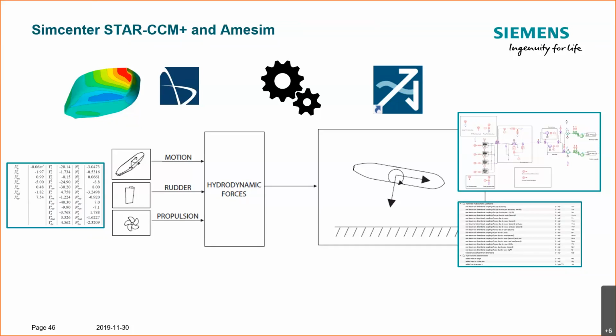And the big advantage is, because that is oftentimes omitted in both direct and indirect maneuvering simulations, we can include a very sophisticated engine model, because apparently all simulations that we've seen so far draw upon the assumption that the engine characteristics and propeller RPM remain constant.